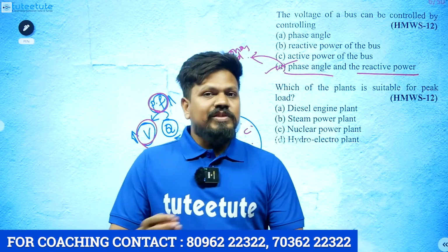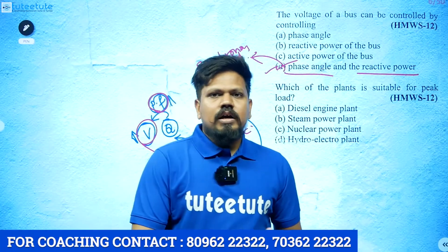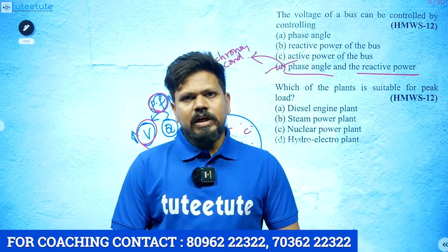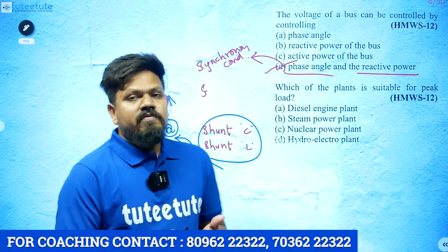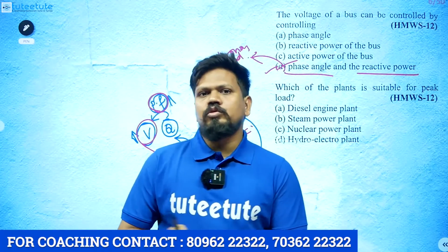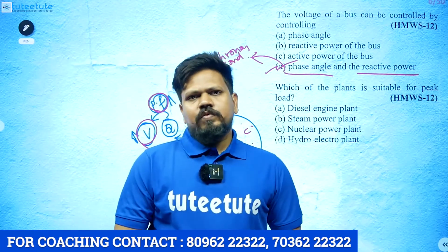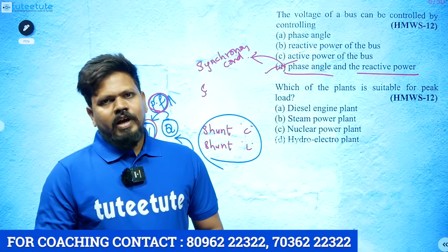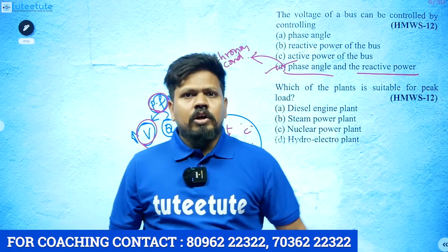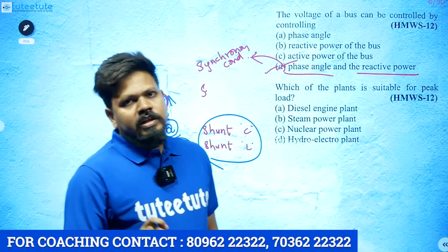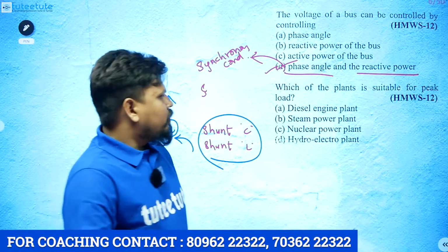How is it possible to increase within a very short time? Whatever generators we are using need to start within very little time. Understanding, right? So whichever power plant has a very short starting time, that type of generator we have to use as a peak load power plant. Whenever load suddenly increases, you have to increase the generation within a very short time. We will see what the short-time operating generators are, which get connected to the grid within very little time.